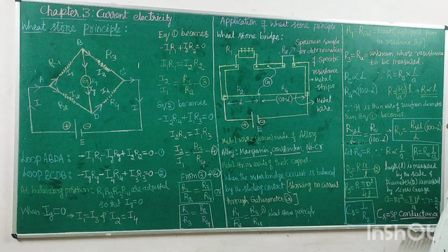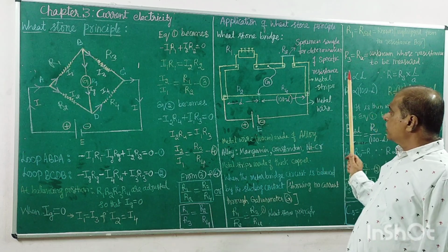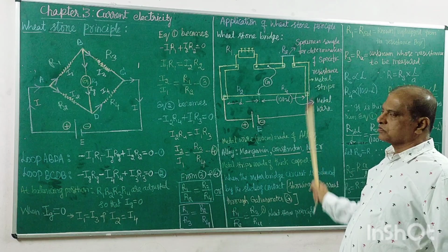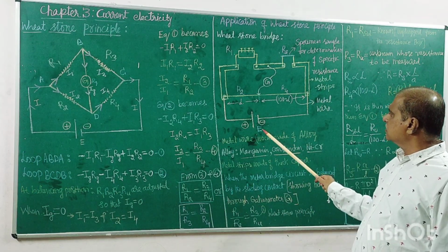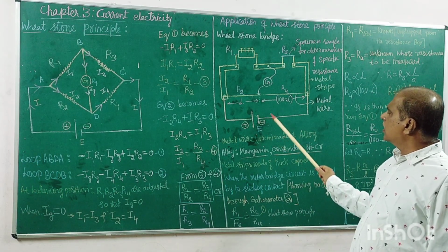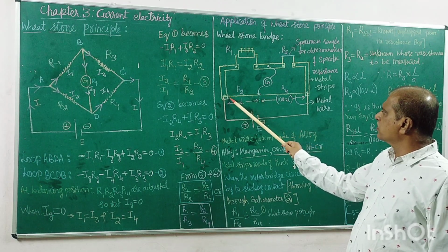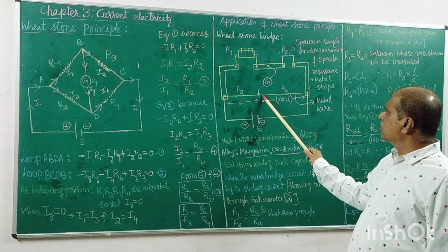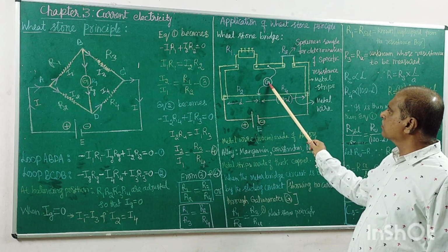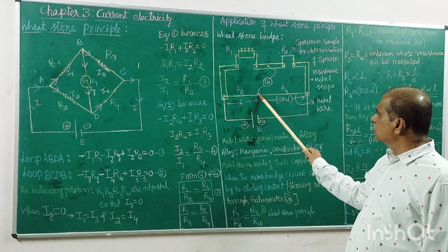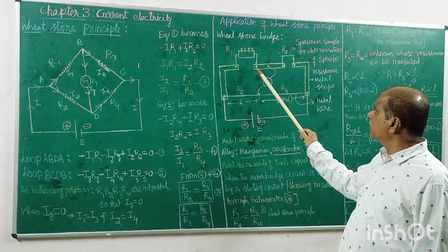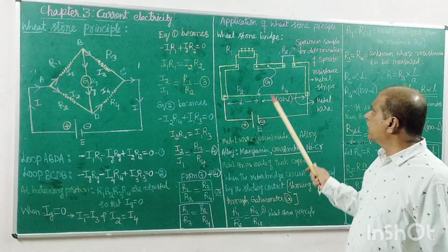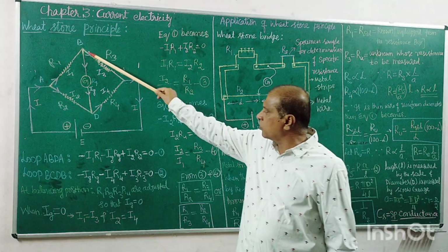So according to that concept, now what else do you have to find out? Now you can go for the experiment. This is the construction. For the experiment, you switch this on and make a sliding contact. You slide it from here, you get one deflection, the deflection decreases, and at some other point there is no deflection in the galvanometer. That is, at some point like this, no current is flowing through the galvanometer.